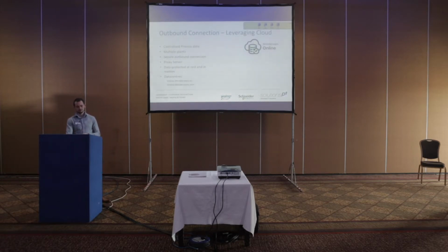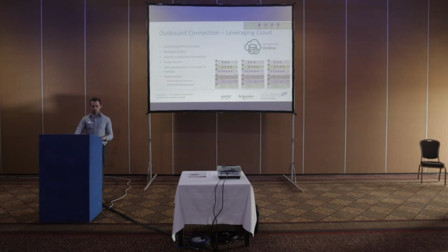And this is certainly extending out even further, so we could have multiple plants, we could have multiple devices, and now with the advent of things like cloud historians through our Wonderware Online scenario, we can get data from even more places. And it's important that we extend that data and push it out through that same layer and that same security method through that demilitarized zone. We do it through proxy servers. We make sure we utilize IT-friendly ports such as 443. We make sure we introduce whitelisting and endpoints and things like that. It's really key that we're securing that outbound connection, and it's a push from that manufacturing layer out to that cloud environment.